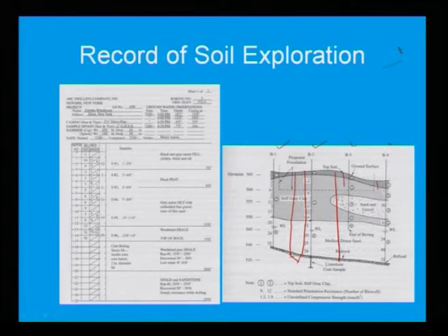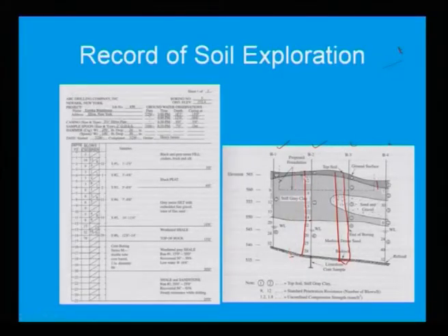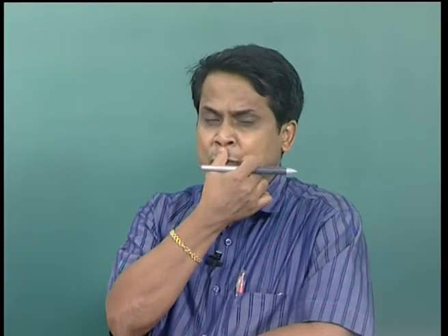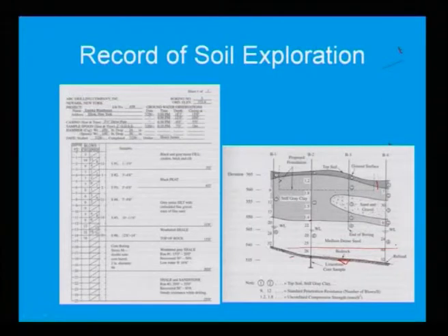The moment you go for a deep foundation in the form of pile, you want to locate some hard stratum somewhere else, either sand, gravel or bedrock. If you look here, this bedrock is varying at an elevation of almost 540 to 535. Bedrock is not supposed to be uniform. It is not necessarily uniform throughout. It may vary in this way, or it may be constant throughout.